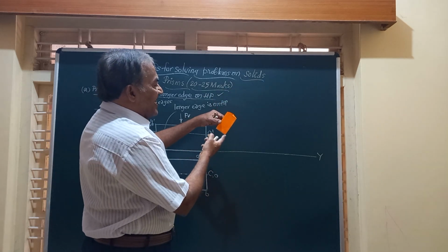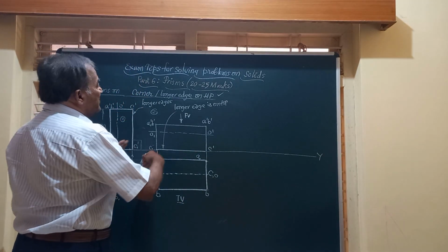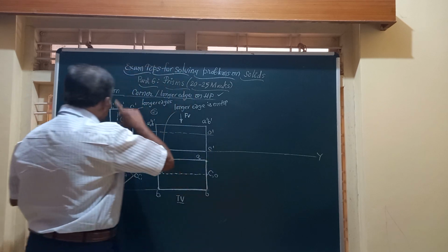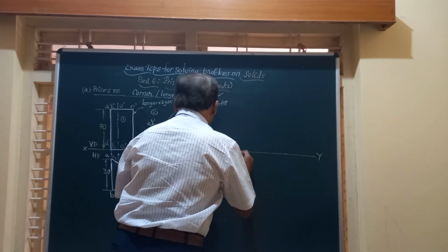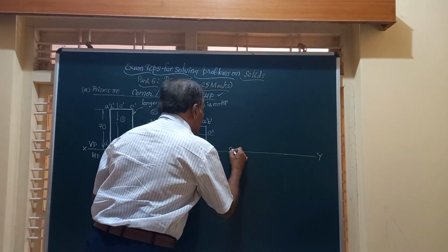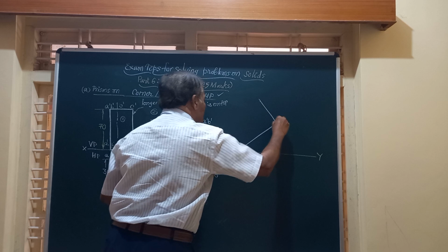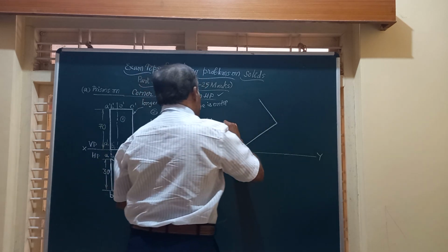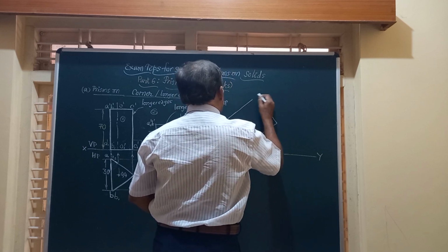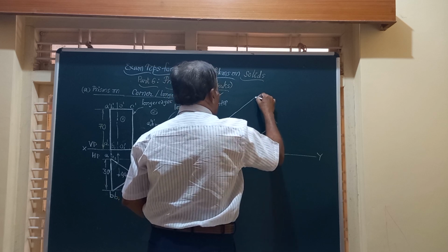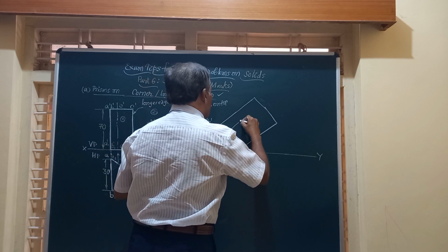If it is resting on a corner, then again friends, after obtaining this figure, we have to reproduce this figure here such that it is at an angle. So this corner is going to be C1 dash, and friends, whatever angle they give, for that angle we are going to draw the projections of the solid. So instead of the rectangular face, if the object is resting on a corner, this is how the solid will look.